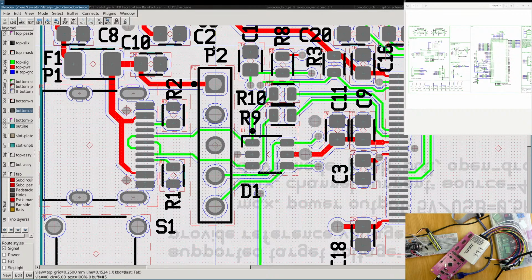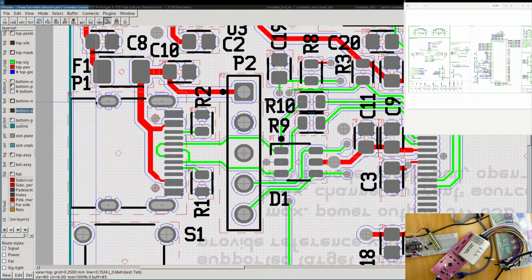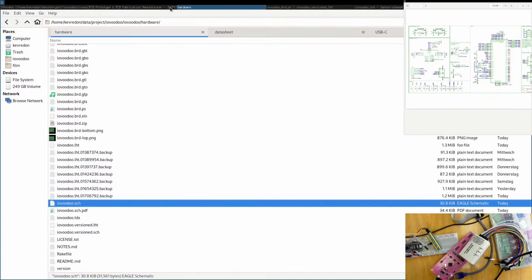For example, if you have board edges on the side where you connect a connector, and you have a hole still for mounting, and you have 2 pads on each side. The hole is just for mounting, it's not for connection, and you want the 2 pads on either side to be completely disconnected. There's no way on JLCPCB to do that except to add a note and hope that they read the note file and they don't plate your hole with the connections. Professional houses have different files.